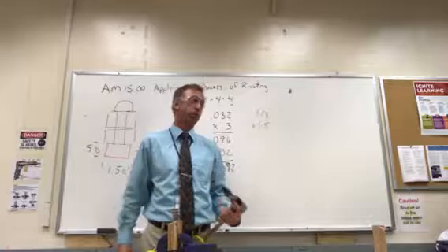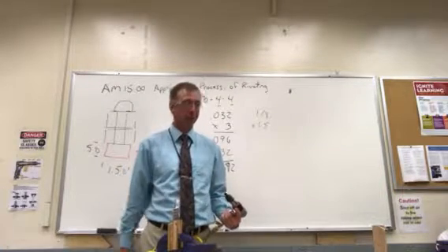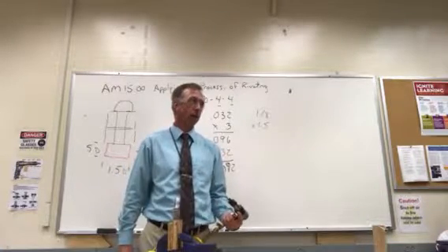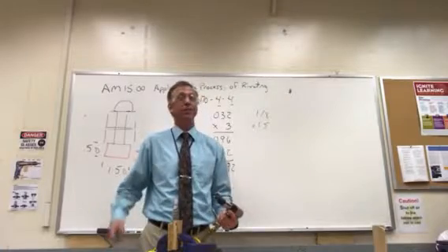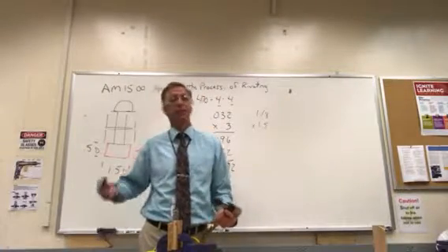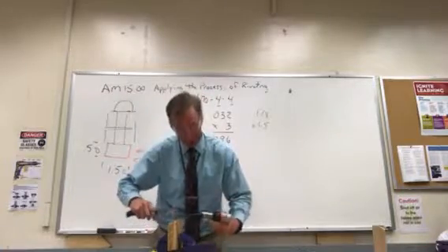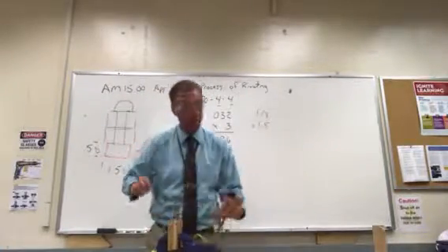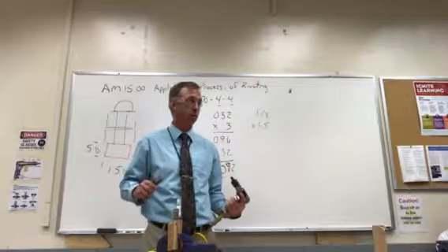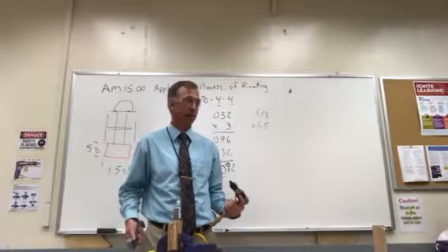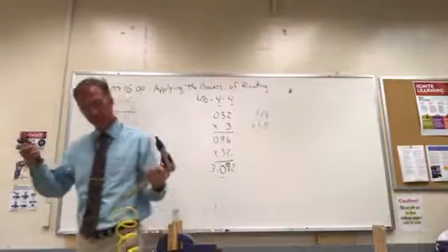What happens if I over rivet it? It's going to be flat, and you're going to have to take it out. So, it's easy to rivet, it's difficult to unrivet. That's why it's just pop, look at it, pop it again. Okay? And that's all we want to do. Any questions about that? All right, who's up?